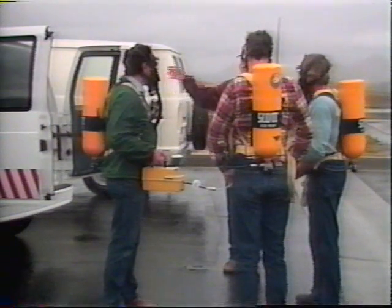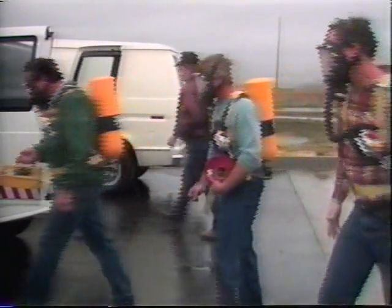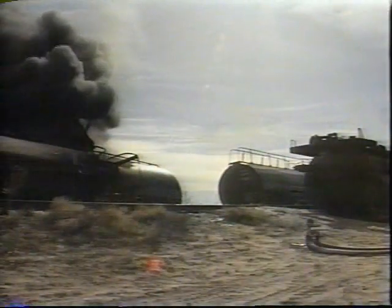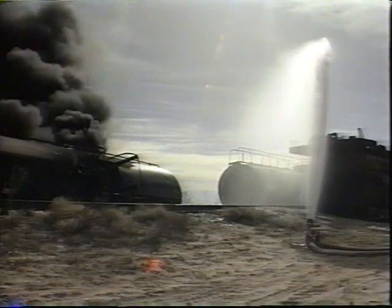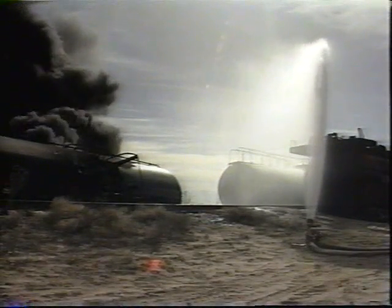Monitoring personnel should be aware that conditions can suddenly change from non-hazardous to hazardous. Acutely hazardous concentrations of chemicals may persist in confined and low-lying spaces for long periods of time. Look for any natural or artificial barriers, such as hills, tall buildings, or tanks, behind which air may be still, allowing concentrations to build up.